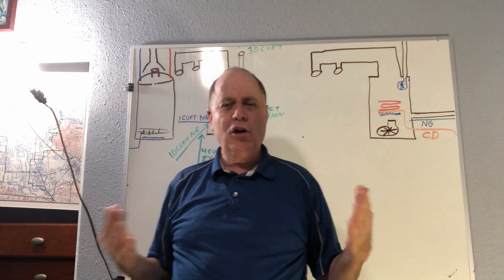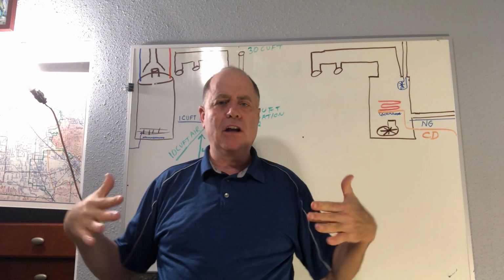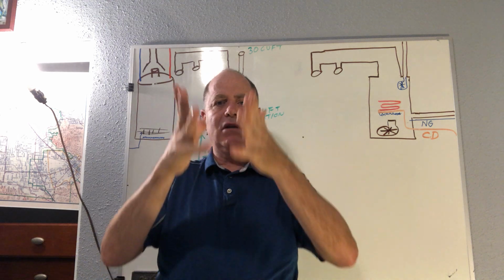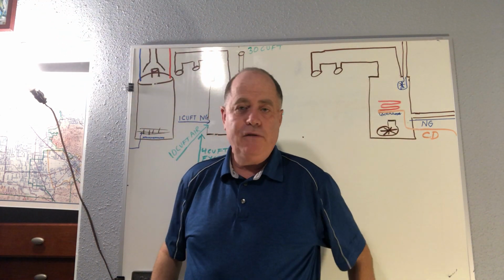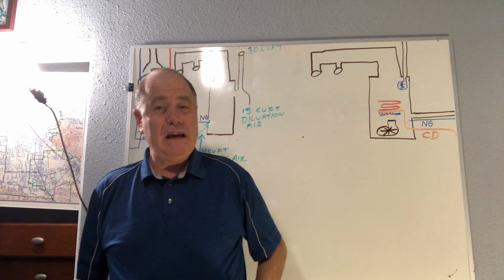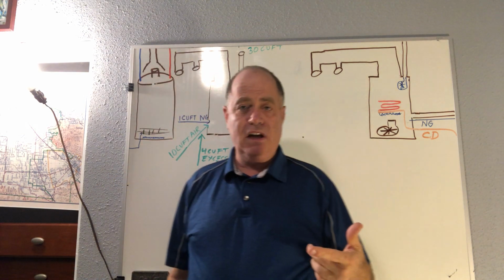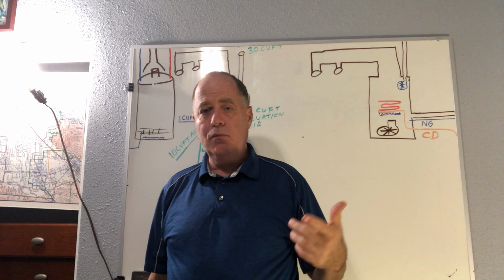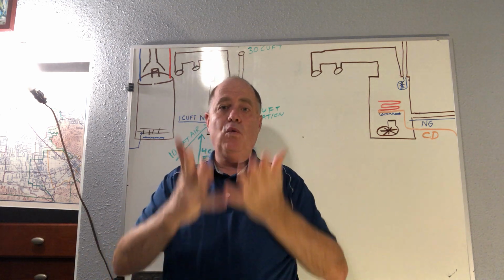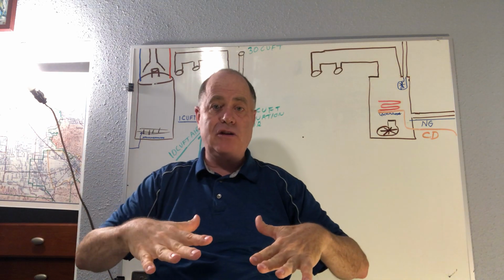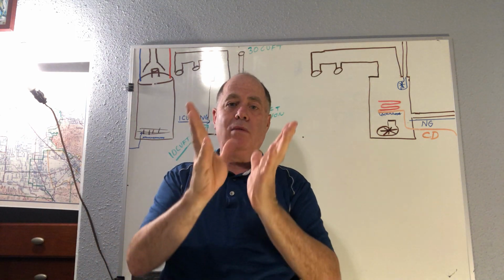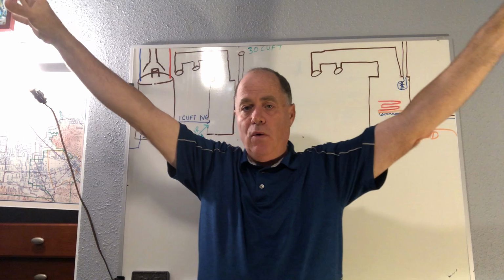And if you're working in there, this natural flow of air coming in, heating up and going out provides better air for you. We have this concept over and over again where air comes in down low, warms up, and goes out. That's how we have natural infiltration, air leaking into a building, warming up, and exfiltration going out.